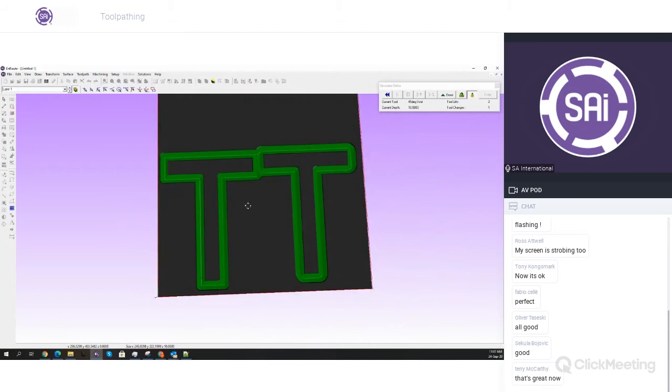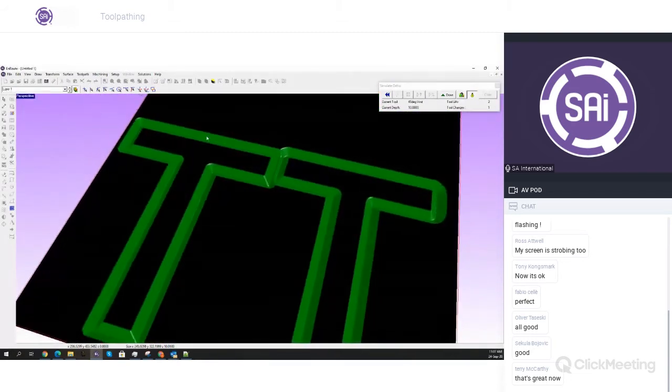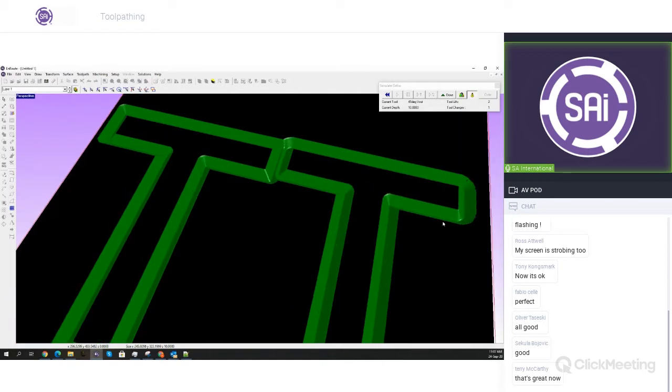So as you can see, if you're using a bevel tool, checking or unchecking the sharp corners will have a tremendous effect on the, as you can see, the top corner here is always going to be square on both sides. But if you're going to use the conic tool, the tip will cut with square corners in a square, and with the other ones, it'll follow that rounded shape that's made by default. So that is something you have to keep in mind.